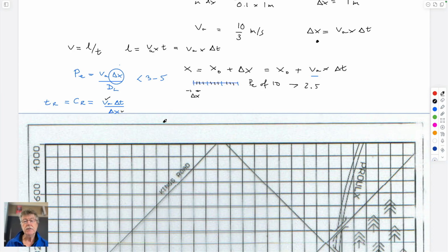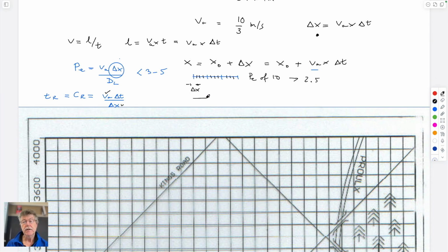And so you could imagine that if you have a particle that's streaming down here at high velocity, then if you have, by trying to limit your Peclet number, made lots of small divisions, then that particle can go upstream and go right the way across an element and go downstream without ever registering in the next element. And so what the Courant number means is that the velocity times time is the length of one element.